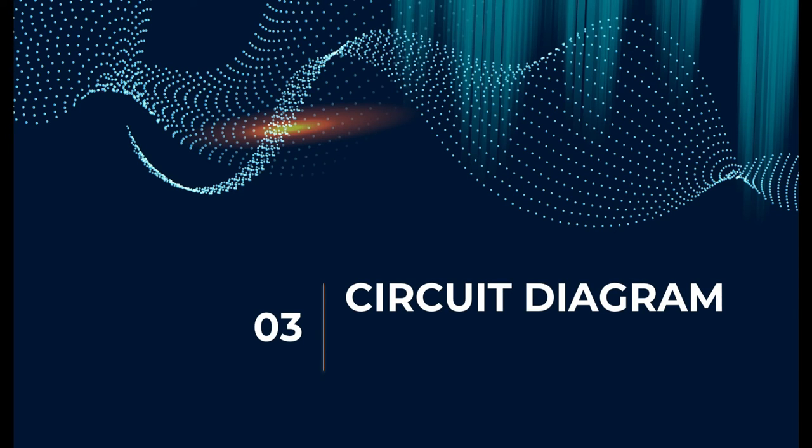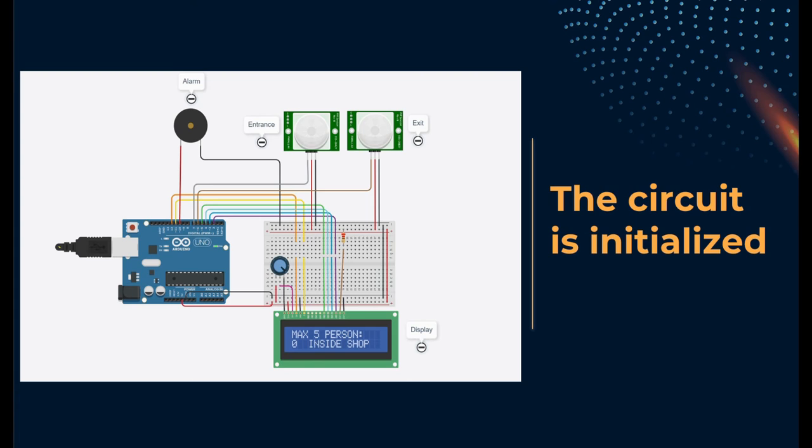Next, we will look into the circuit diagram. This is the schematic circuit of our system. It consists of an Arduino Uno, a pair of PIR sensors, for entrance and exit, an LCD, a potentiometer, and a buzzer. Once the system is on, the LCD display will show the maximum, and on the second line it shows the number of people in the shop.